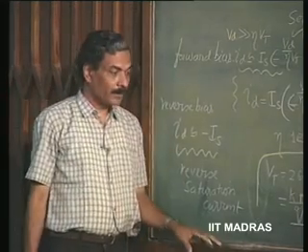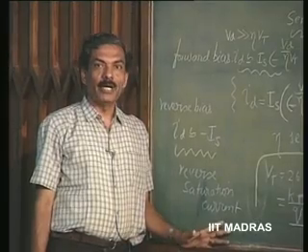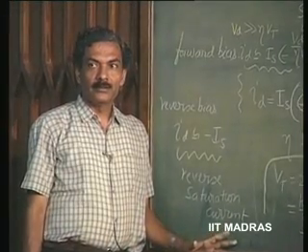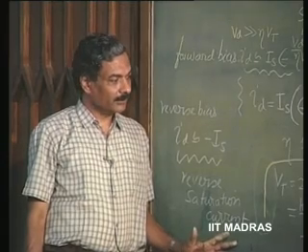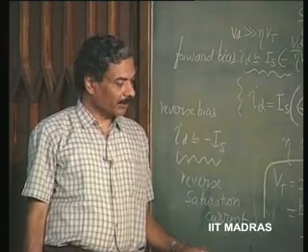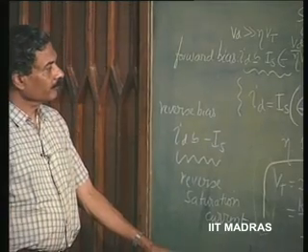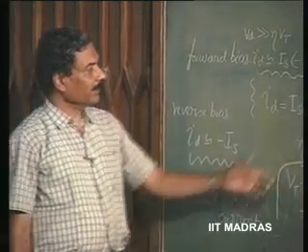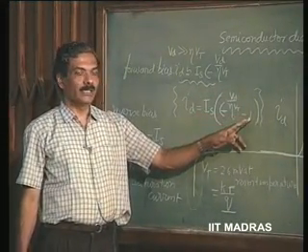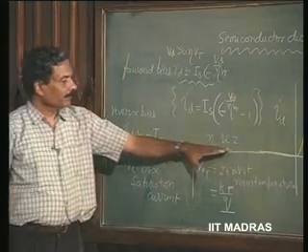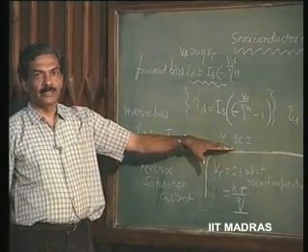Typically this current may be of the order of picoamperes. For most of the small signal diodes, discrete diodes, this may be of the order of picoamperes. Now, you can therefore imagine that if the forward current is of the order of milliamperes, this one can be clearly ignored, and you can also say that for all practical purposes almost no current flows when the diode is reverse biased.